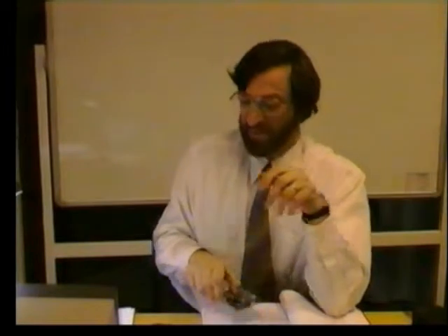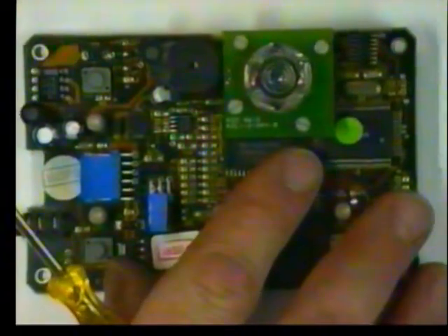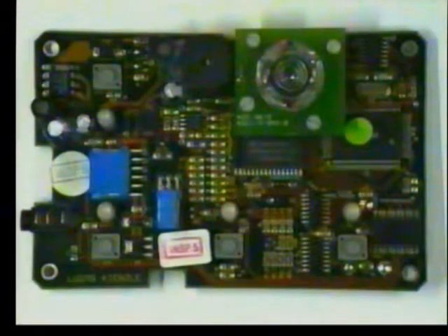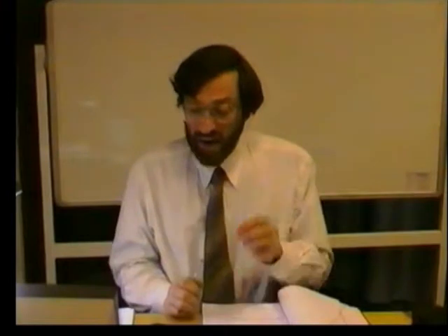So we've discussed the 3-wire techniques, SPI, and the 2-wire techniques, I2C, but the really interesting recent developments are the 1-wire devices. I've got an example here. This is the circuit card from a tachograph in a lorry, and it's used to monitor the whole of the driving situation over a 24-hour period. What is required is that the driver carries one of these things, a small button memory.